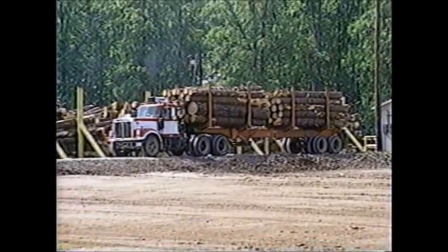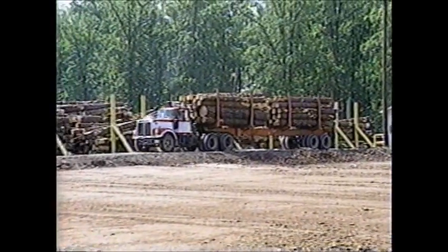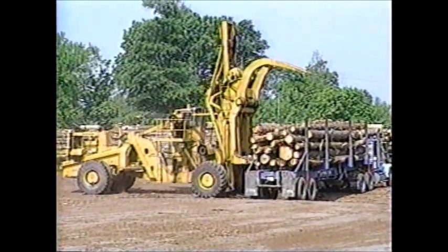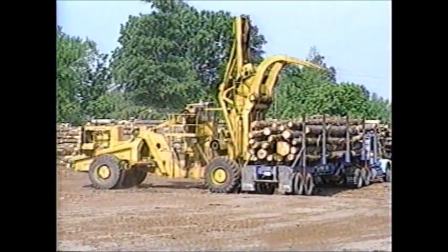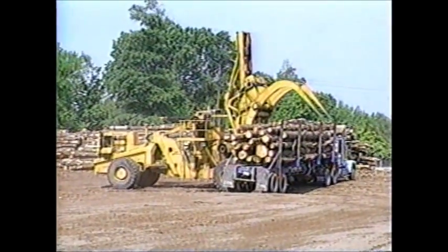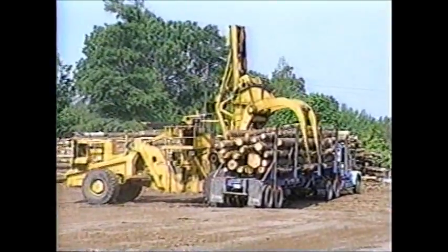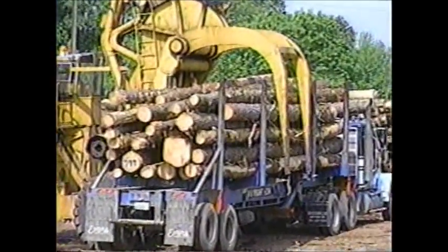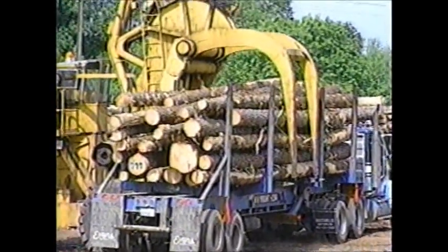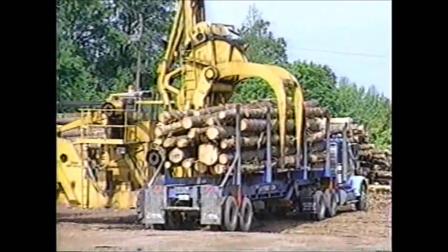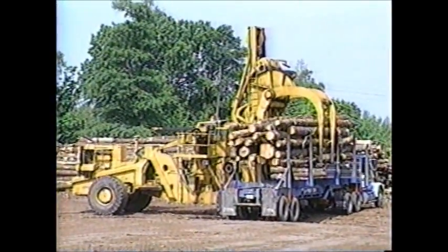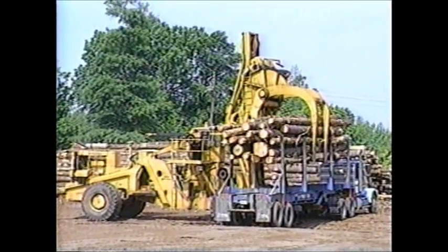Incoming truckloads of logs are first weighed. The volume of material required for plant operation prevents purchasing logs by measuring or scaling them, so purchases are made on a weight basis. The principal species used in the manufacture of construction and structural plywood at this plant is southern yellow pine, but the manufacturing standards of the American Plywood Association classify over 70 species of deciduous and coniferous trees which can be employed in the manufacturing process.